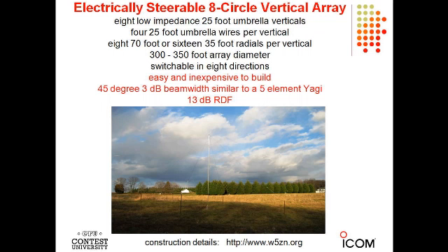You don't need a foundation for these antennas. It's completely unnecessary. Mine mounts on a 2-foot long piece of rebar. But I'm sure there's a whole bunch of schemes you could come up with. You just need something to mount the antenna on that's strong enough so that it won't sink into the ground or fall over. Because you've got the top loading wires that are supporting the antenna, you don't need to worry about the antenna falling over. So there's no need for a foundation. So it's just that simple.